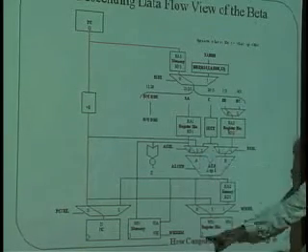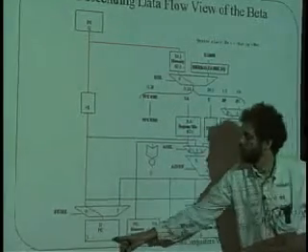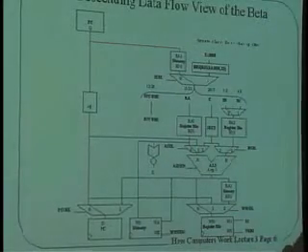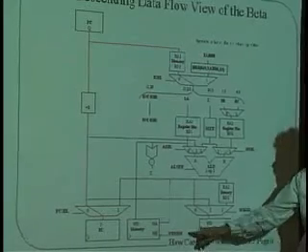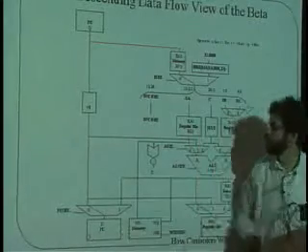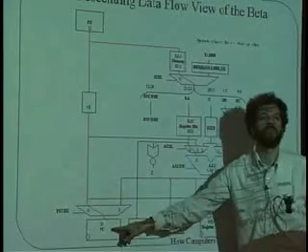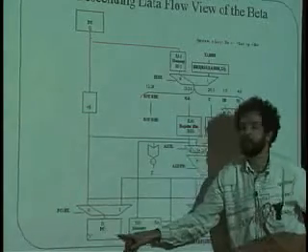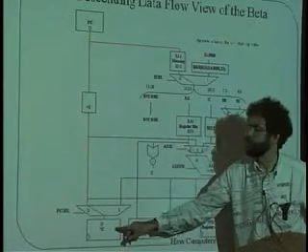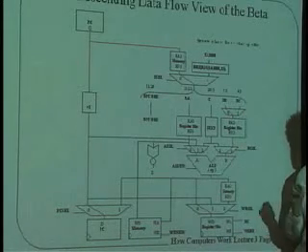Part of the idea here is that you'll notice the system here has no clock except for down here. A clock is given by the arrow sign on the left-hand side here, okay? And so every time we want to process the next instruction, there's going to be an upward going clock on each one of the arrows down here. And the PC will always be incremented, or it will always change. So the clock that goes into here, notice that there is no E here. So this part of the storage, the register that is the PC, will always be written every clock cycle, every time the clock goes off.